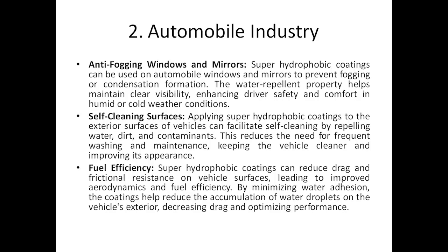Automotive industry: anti-fog windows and mirrors, self-cleaning surfaces, fuel efficiency. Fuel efficiency we can separately discuss: super hydrophobic coatings can reduce drag and frictional resistance on vehicle surfaces. How? Leading to improved aerodynamics, and because of the aerodynamics, we can also say it increases fuel efficiency. By minimizing water adhesion, the coating helps reduce the accumulation of water droplets on the vehicle's exterior, so decreasing the drag and optimizing the performance. That's how it helps in gaining better fuel efficiency.